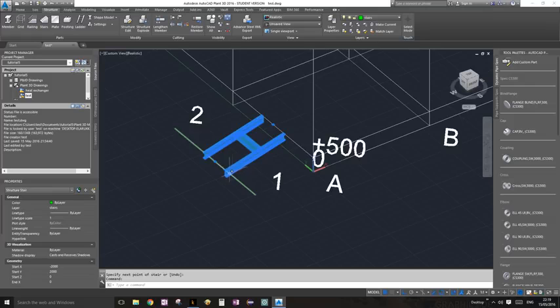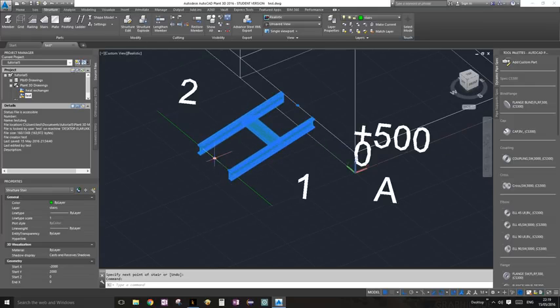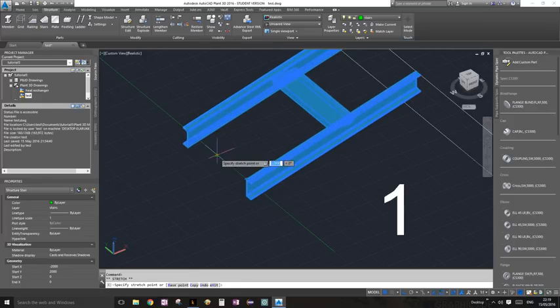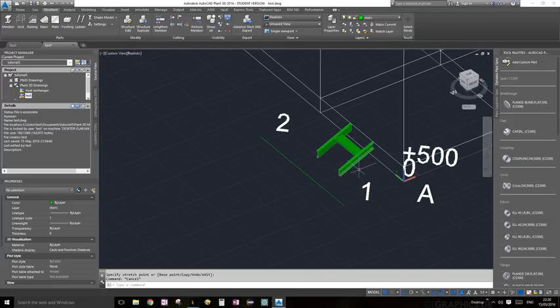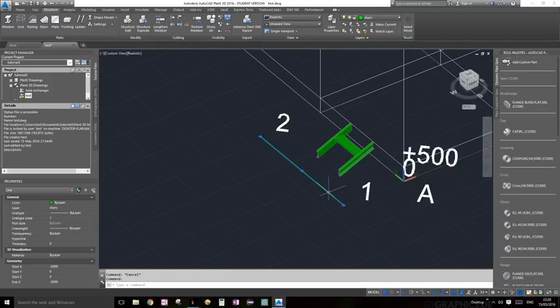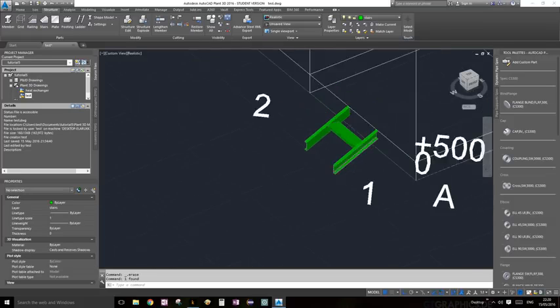Now actually this is a good point. It does look pretty ugly. You can change that. If you select your stairs, you see there is a little grip point there. You can drag it and make it shorter because it looks so ugly. You just need one stair there. Perfect, that looks a lot better. But if you already knew the distance your stairs needed to be, you could use the line to do that perfectly. But you're gonna need a line anyway because you need to choose a midpoint, or at least a point that your stair would snap onto at the beginning. So there you go. Go ahead and just delete that line there. I think it should work. There we go. That's it.